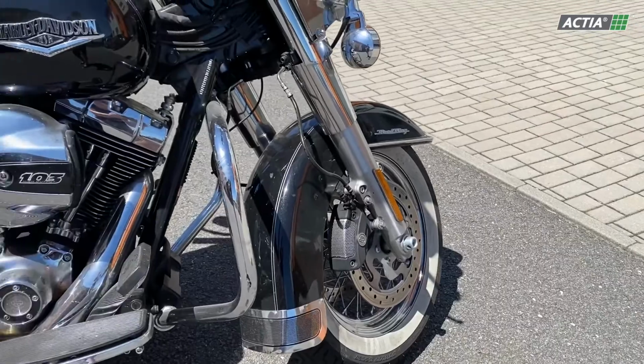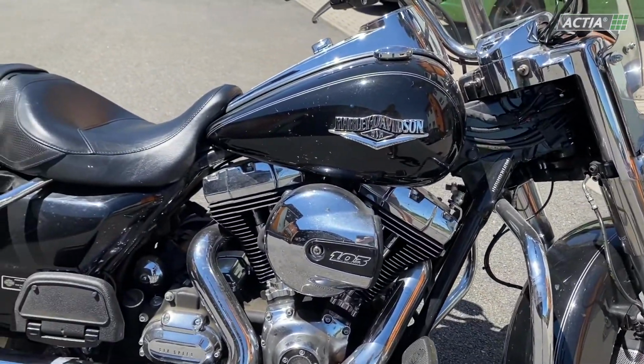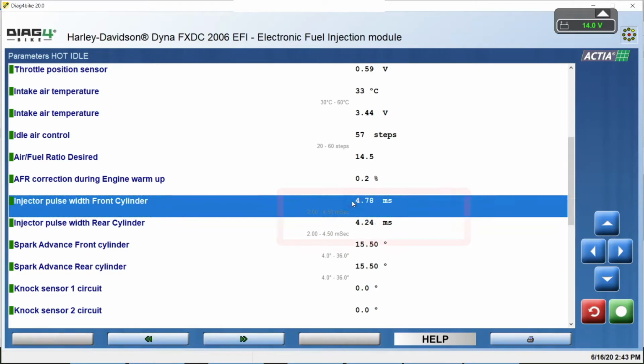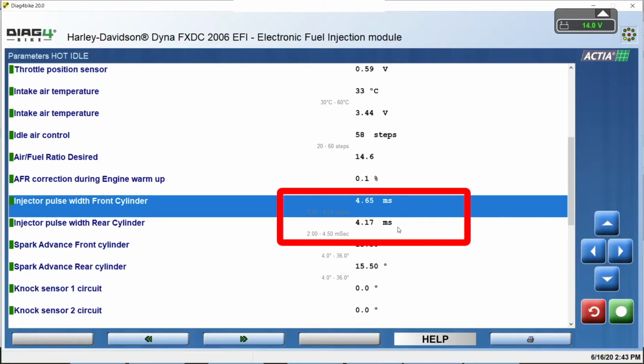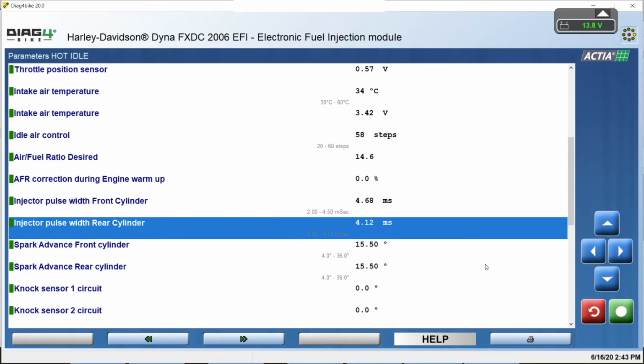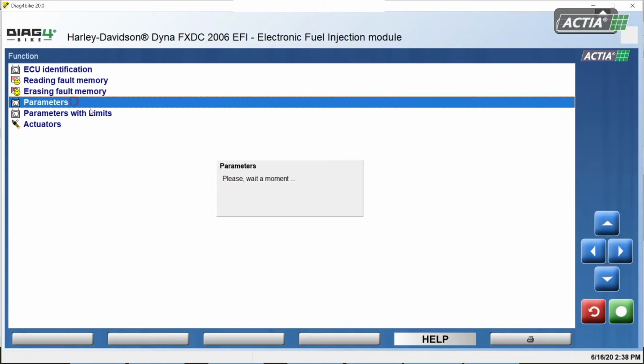You can also quickly and easily pinpoint issues with low fuel pressure at the injector in an injection system with a functioning closed-loop lambda control, without having to disassemble the fuel piping. This fault can be checked by measuring the injection time at idle speed and increased idle speed. For example, a 20% lower fuel pressure will increase injection time by 10%.